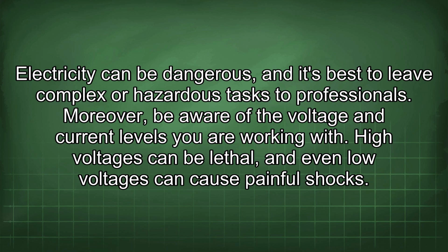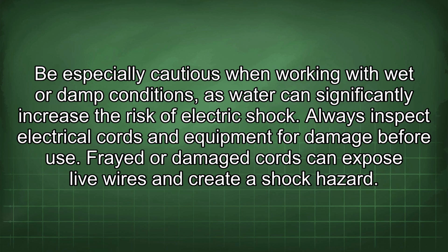Moreover, be aware of the voltage and current levels you are working with. High voltages can be lethal, and even low voltages can cause painful shocks. Be especially cautious when working in wet or damp conditions, as water can significantly increase the risk of electric shock.